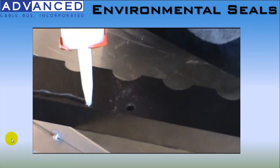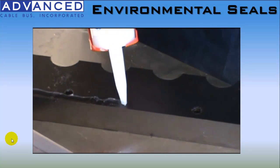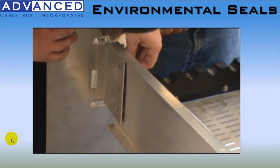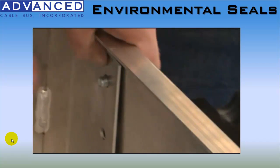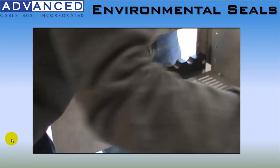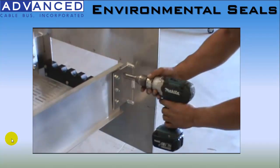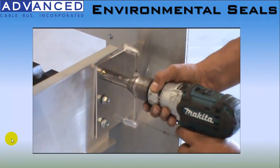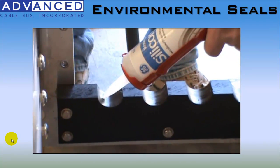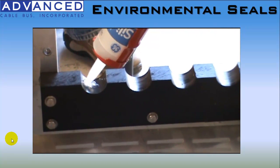The first step in installing the seal block and the cable is to apply the silicone sealant along the edge of the bottom seal block, and then return the seal block to its original position. This is followed by mounting the seal plate to the wall and then to the cable bus section that is being attached to it. On the seal plate there will be tabs that will work just like a splice plate when you connect two pieces of cable bus housing together.